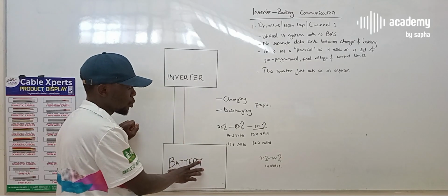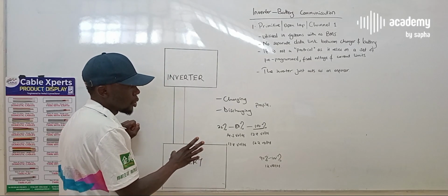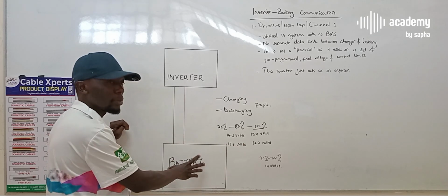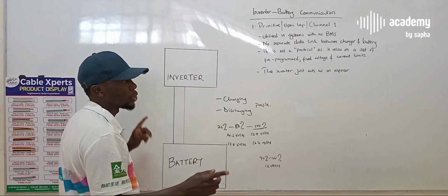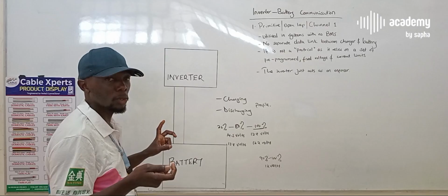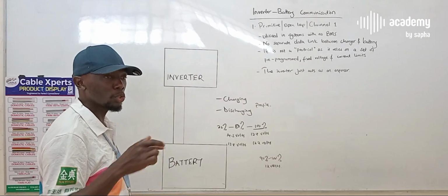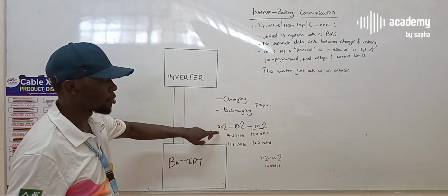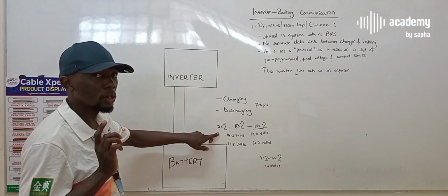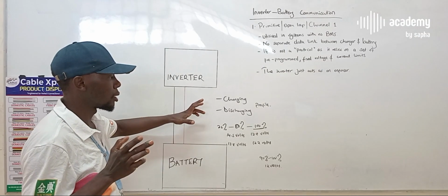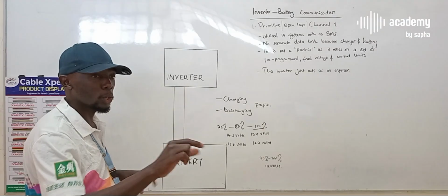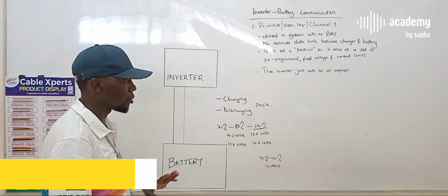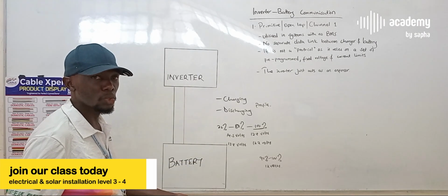And for smaller systems, as we said, we don't have much to discuss here, but when we start increasing the battery capacities for this same protocol, we shall look at how we introduce opposite takeoffs to ensure that the inverter is reading information from the batteries all across the battery bank. So we shall look at these charging and discharging profiles, and then probably after that we can also look at the installation design, to ensure that the inverter is reading all the information from the several batteries. After 4 batteries, you need to change the installation design.